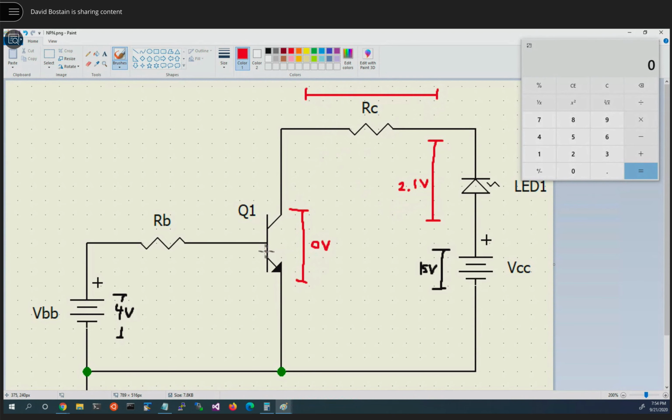We also know that if we're in a saturated circuit, the voltage drop across the base emitter is 0.7 volts. So we know a lot about the voltages right now. Let's see if we could actually make it around either of these loops with reasonable values. This is ground. We can't see it, but it's down there.